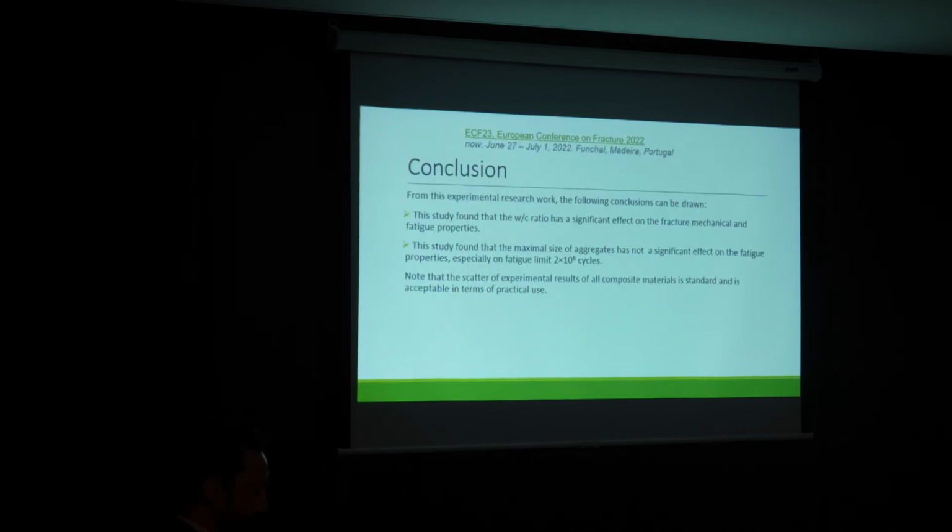Okay, let me conclude from this experimental research work. The following conclusions can be drawn. It's quite easy: the study found that the water cement ratio has a significant effect on the fracture mechanical and fatigue properties. This study didn't show any significant effect on the fatigue properties, especially on the fatigue limit, for different sizes of the aggregates. We only know that the scatter of the experimental results of all composite materials is standard, and it's acceptable for this type of practical use.